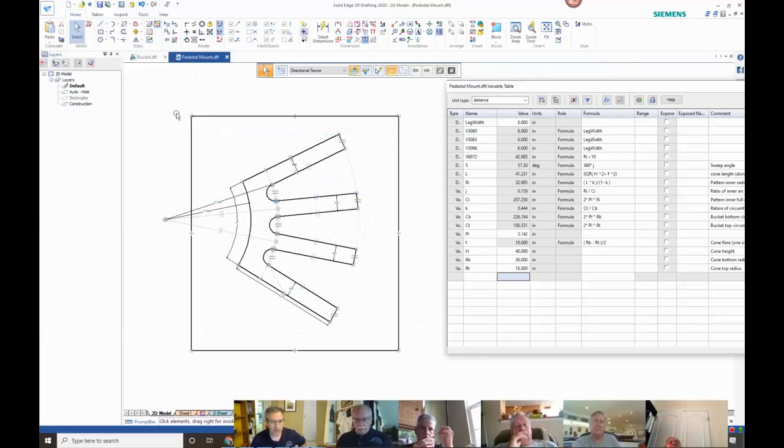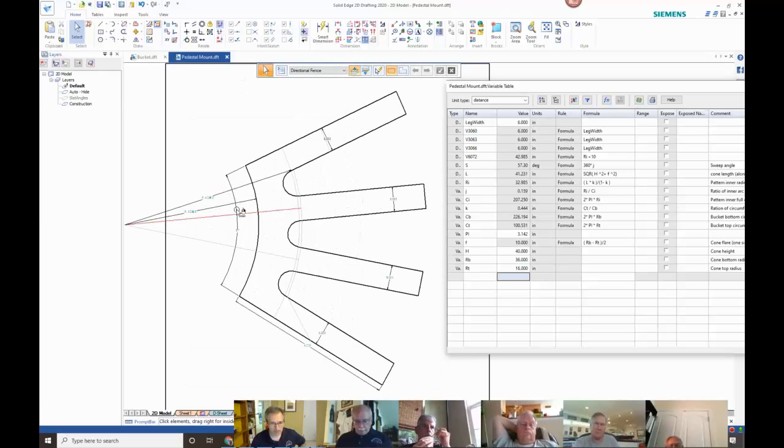The fill command is something that you would use to create your photo etching stuff. One other thing I hadn't mentioned is all of these handles I was telling you about that show the relationship. You can turn them off so they're invisible, but they're still active. So that is this one. It just toggles the display. So if I click that one, all of those handles go away. It cleans up the image somewhat.